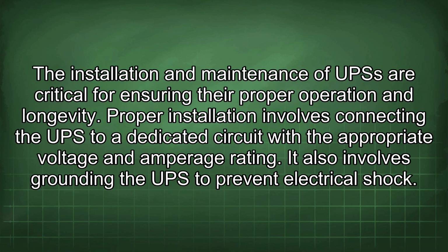The installation and maintenance of UPS are critical for ensuring their proper operation and longevity. Proper installation involves connecting the UPS to a dedicated circuit with the appropriate voltage and amperage rating. It also involves grounding the UPS to prevent electrical shock.